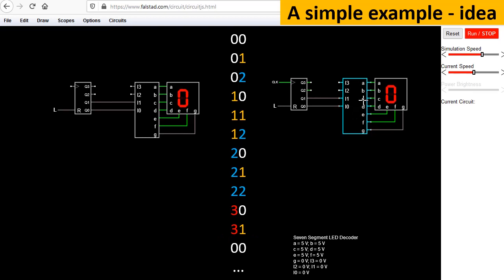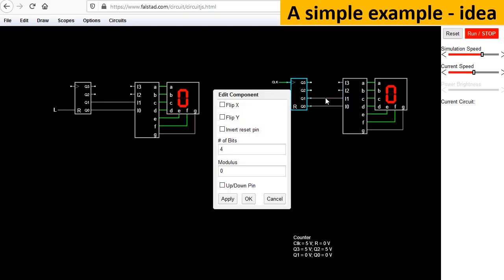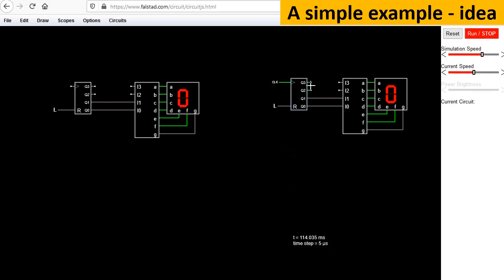We need only digits from 0 to 3, so 2-bit counter would be enough, but the minimal value here is 3, so we'll just not use those 2 bits. Now let's prepare functions to design circuits to reset counters.